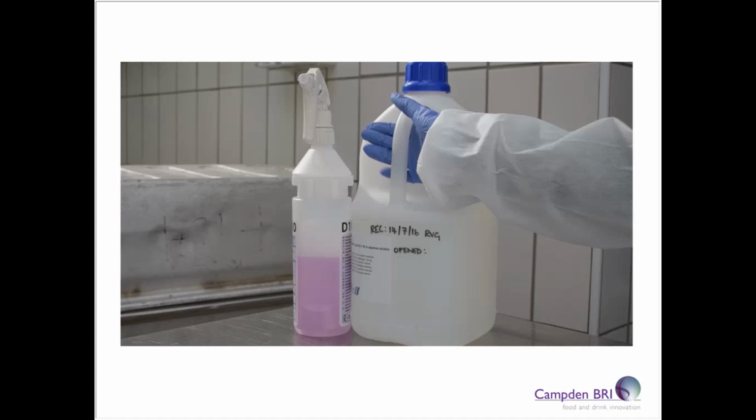This is just an example of intermediate containers that the products may be stored in. It's very important they are labelled correctly so that we don't mix up our chemicals. And again, this is a common fault at audit where small amounts of chemicals are used online. So rather than taking a large IBC or a 25-kilo drum, they're poured into smaller containers, and it's the inadequate labelling of the smaller containers with dates and appropriate data.